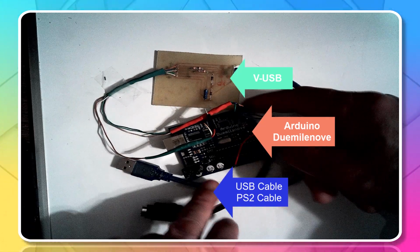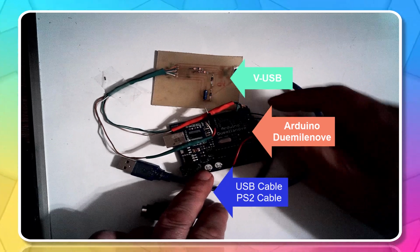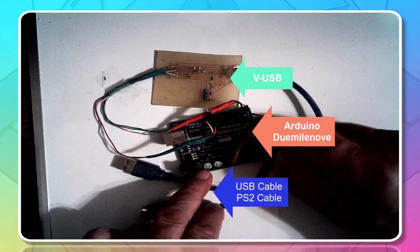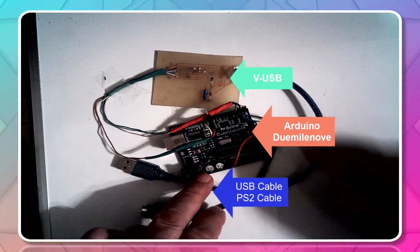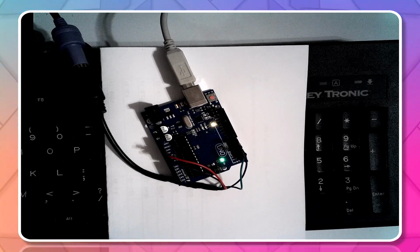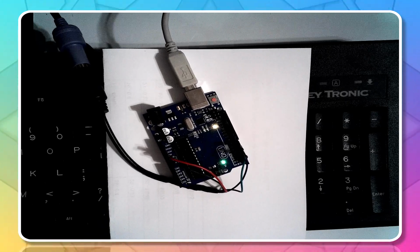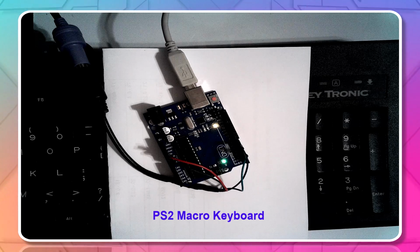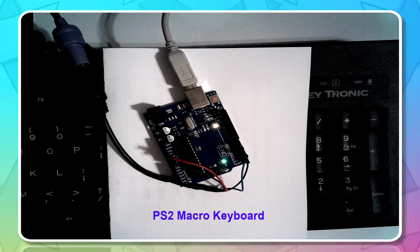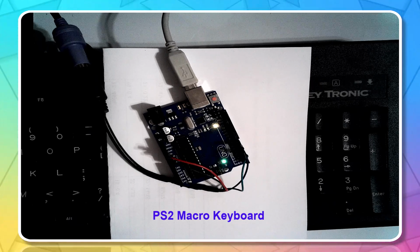After all these years, I began my journey using the original components, but the Leonardo, PS2 keyboard, and VUSB libraries are incompatible. So, I did it in a different way. Let me explain. I used PS2 Key Advance and PS2 Key Map Arduino libraries to obtain the hexadecimal codes of every single keystroke and for some combinations of keys. I changed the original code to distinguish between Alt-Left and Alt-Right keystrokes to extend the number of possible combinations. I used all the function and multimedia keys to reassign the meaning of them or to assign new macros.